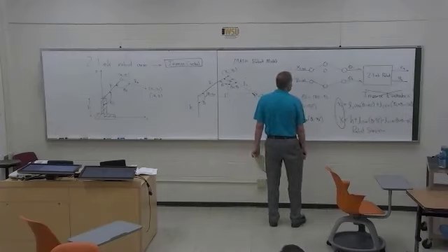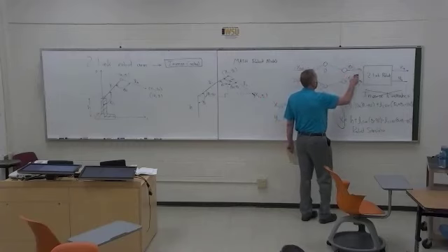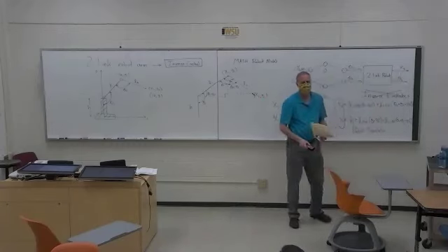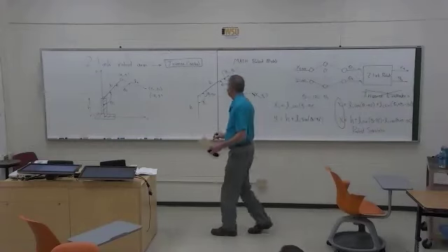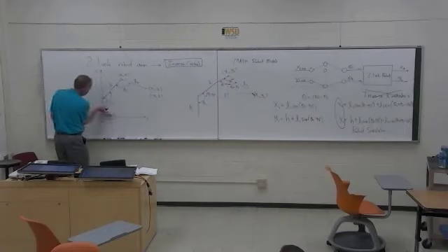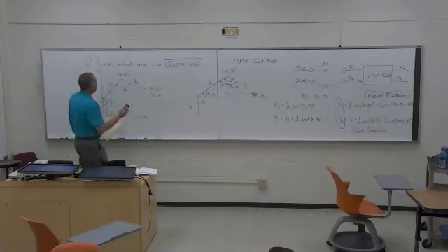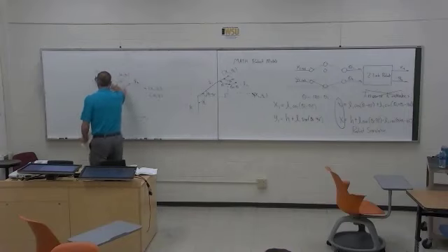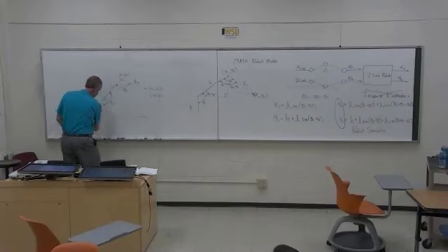The strategy of inverse control is you put a bunch of different thetas in, and you record where the end shows up. You take the robot, and you put in a bunch of thetas, so you vary this angle, vary that angle, record values here, and then we'd end up with a data set with all those thetas that go in, and then where the end came to be.